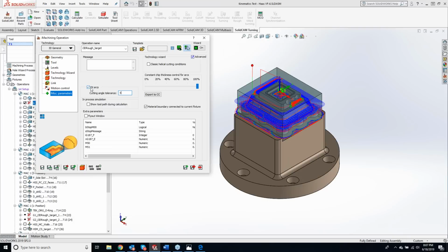So by the fit arcs, from my working on the machine, I would want to use fit arcs because we had not brand new machines, but we did have older machines. Greg, what are some of the new machines that really can chew through the point to point? Anything like a Makino style machine that has its own spline approximation, where you can feed it points and it determines what the appropriate path to take is based off the tolerance of the machine and the settings that you have, would be a good example of something.